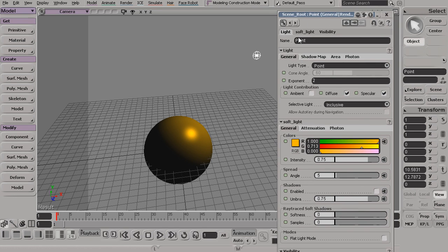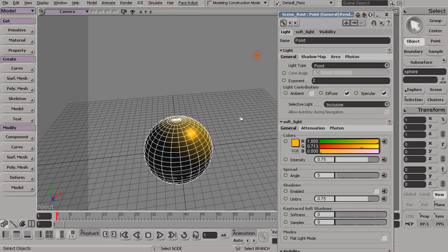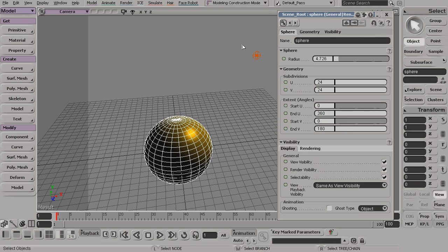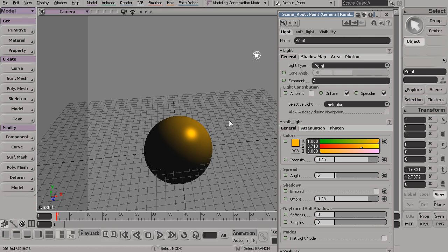Now, that's not a feature that we necessarily have to go with. We can actually lock a property page down. At the top of your property page, you have these three little icons. Over on this far right hand side, we have this little lock icon. If I click on that, you can see now, even if I select another object, this property page doesn't update. It'll always stay locked to whatever I currently have active. Now again, if I set this back to a recycle mode, which is this middle button, it should automatically change depending on what I have selected.